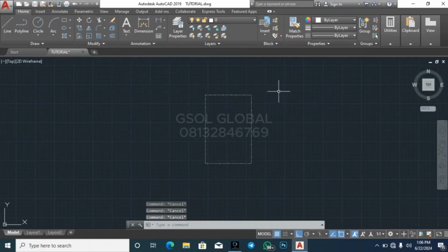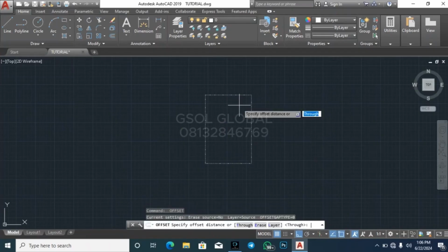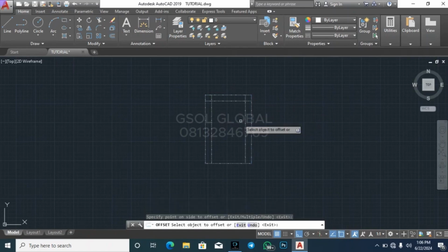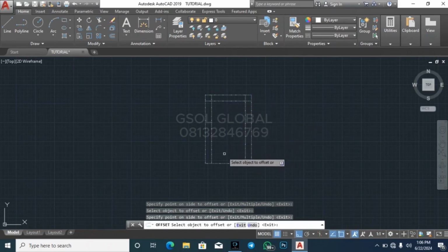First of all, you are going to take note of the distance of the building from the fence, from each side, from this side, this side, this side, and also this side. But let's start from the rear view. Remember, we are going with the most critical. So offset at least 2 meters from behind, 2 meters from this other side, and 2 meters from this other side. Let's see if this will work. If it does not work, we have to readjust.